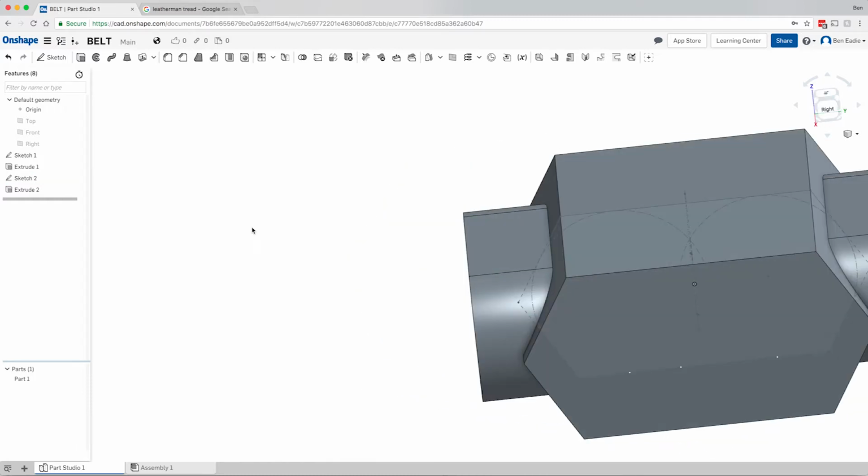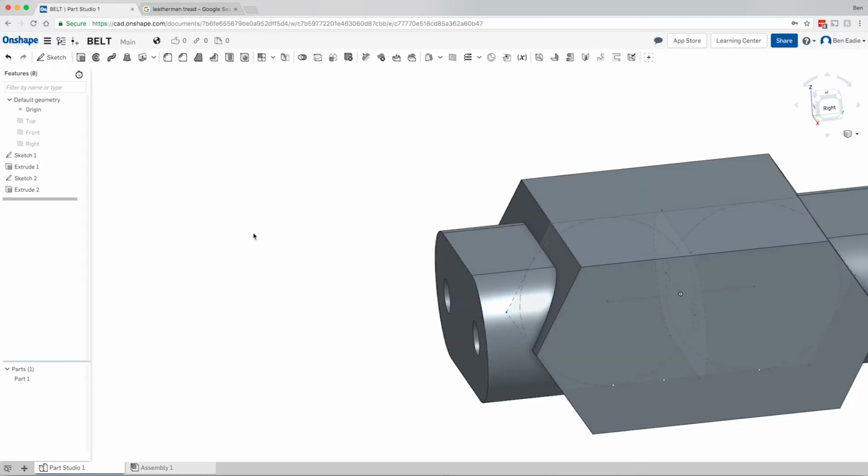Now, if you're creating another sketch on a face or something like that, referring to other geometry in the boss isn't necessarily the best. I generally try to refer first to geometry that already exists, like planes and origins and possibly a line or a sketch that gives us the rough geometry. Then I will reference other sketches. And finally, worst case scenario is you reference something like a boss. So generally, as a rule, you always want to refer to origins, planes, then sketches, and then bosses, because faces and stuff can cause issues with CAD.